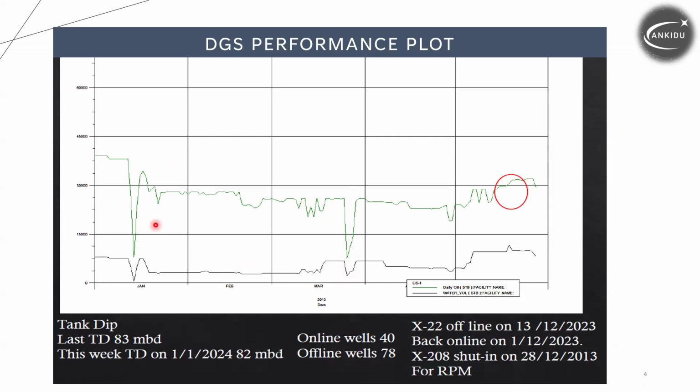So you can see from the plots, from these trends, it's going down in terms of the production rate. So why did this happen? Is it normal? Do we do something, for instance, do we stop the production in the degassing because we're doing a turnaround? Do we have any problem in the degassing itself? If we're doing a turnaround, that means we have to put some wells offline, converting some wells from one degassing to another.